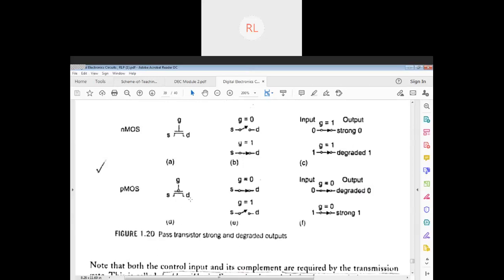If you're using silicon, it's going to be about 0.7, and if you're using germanium, it's going to be about 0.3. These are standard, theoretical values. Practically it could change; it can come down or be a little higher. So instead of 0.7, it can be about 0.75 or 0.8, or it can come down to 0.65, or 0.68 or something at that level.